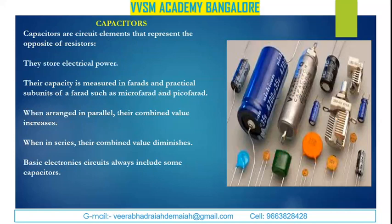Well, capacitors. Capacitors are circuit elements that present the opposite of resistors. They store electrical power. The terminology itself indicates the power of storing electric charge. Their capacity is measured in farads and practical subunits of a farad such as microfarad and picofarad. When arranged in parallel, their combined value increases, unlike that of resistors. When in series, their combined value diminishes.